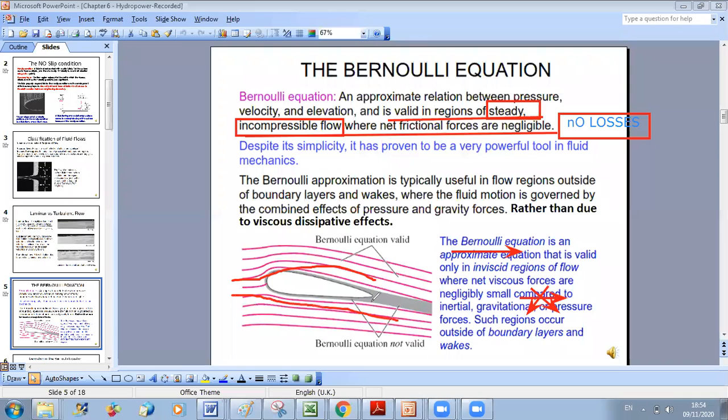And when you have separation of the flow, this creates what is called a wake region, which is like a zone where the velocity of the flow is very small, and beyond it you have motion of the fluid. This is why we call this the wake zone, where we have small fluid velocities, while far from it I have fluid motion.